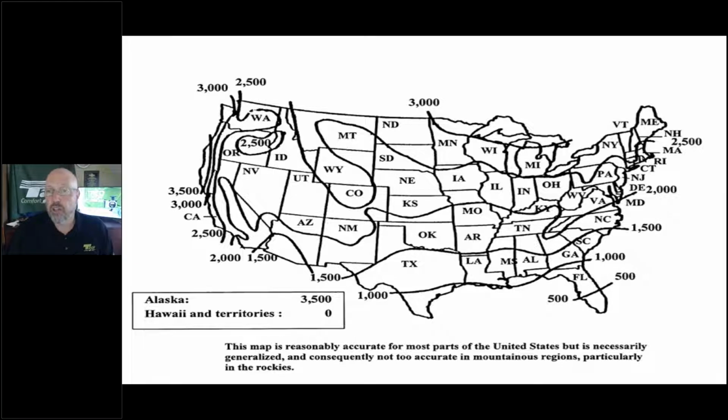The last time I put this presentation together, I was up in Syracuse, New York. So I was hanging out right here when I used this slide last. So I do have some adjusted numbers compared to if I was in Rhode Island or on Long Island where I am now. As you can see up in Syracuse, this line going across here is the 2,500 hour line. In between here, this middle is looking at about 2,000 hours of runtime. That's just your runtime of heating equipment, say out of a 5,000 to 6,000 hour winter.